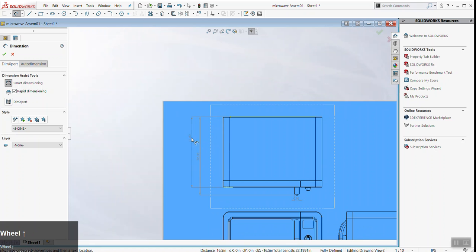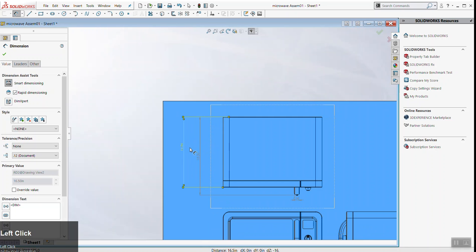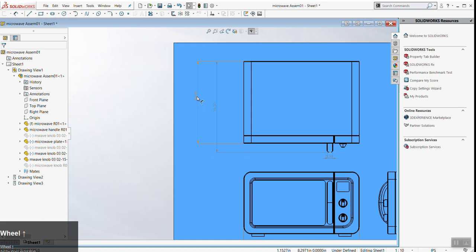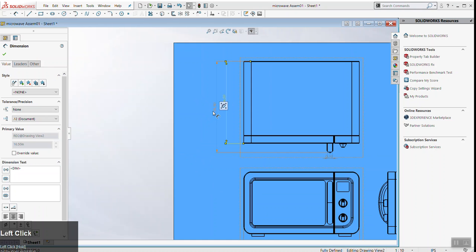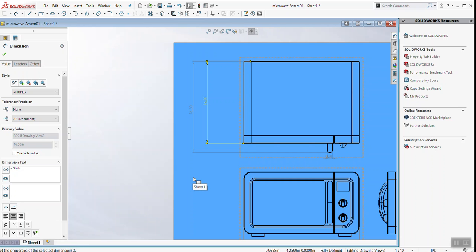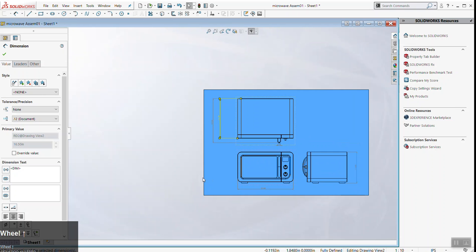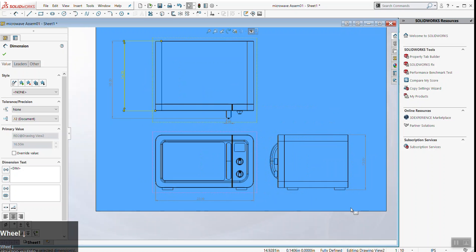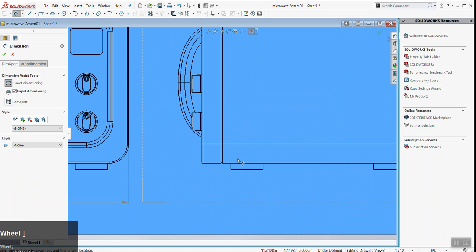This dimension here, here's another no-no. Never do this. Just like you don't want to cross the object, you don't want to cross dimension lines. So that means the widest dimension is always the furthest out, and all the skinnier dimensions stack, getting shorter and shorter on the inside. Now you'll notice, for example, this Z dimension, the depth, I could totally provide on this view as well, right?